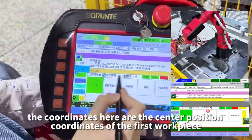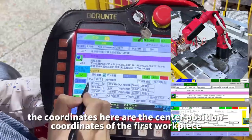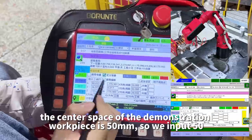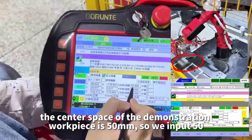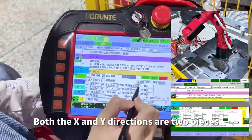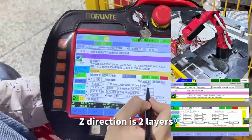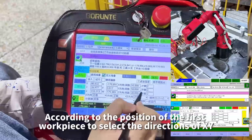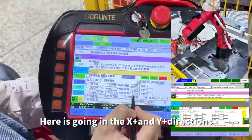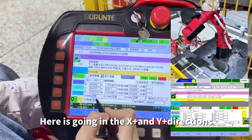After setting it, the coordinates here are the center position coordinates of the first workpiece. The center space of the demonstration workpiece is 50 millimeters, so we input 50. Both the X and Y directions are 2 pieces. Z direction is 2 layers. According to the position of the first workpiece, we select the directions of X, Y; here it is going in the X plus and Y plus directions.